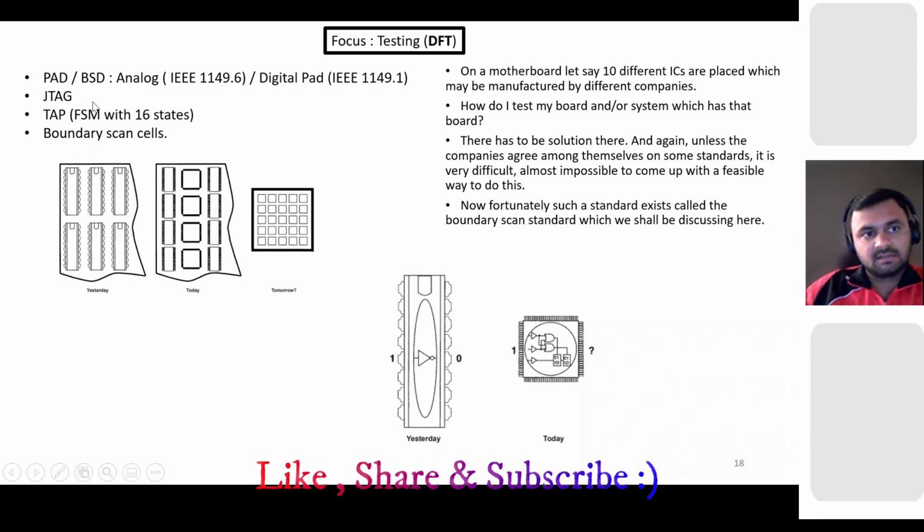JTAG is the group formed by the IEEE, which proposed this. It's very old though, so they proposed this IEEE standard to test that. And we have the TAP, test access port, which is an FSM with 16 states. And we have some boundary scan cells for the top level BST insertion and testing.